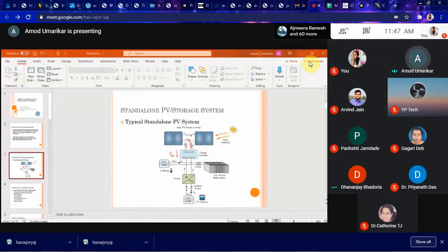So there is a PV, from where the PV power will come. Then the charge controller will process this power, mainly to control it. It will decide whether the panel runs at maximum power or some other operating point. It will also control the output DC voltage, which is connected to a DC load, so its job is also to regulate this VDC.